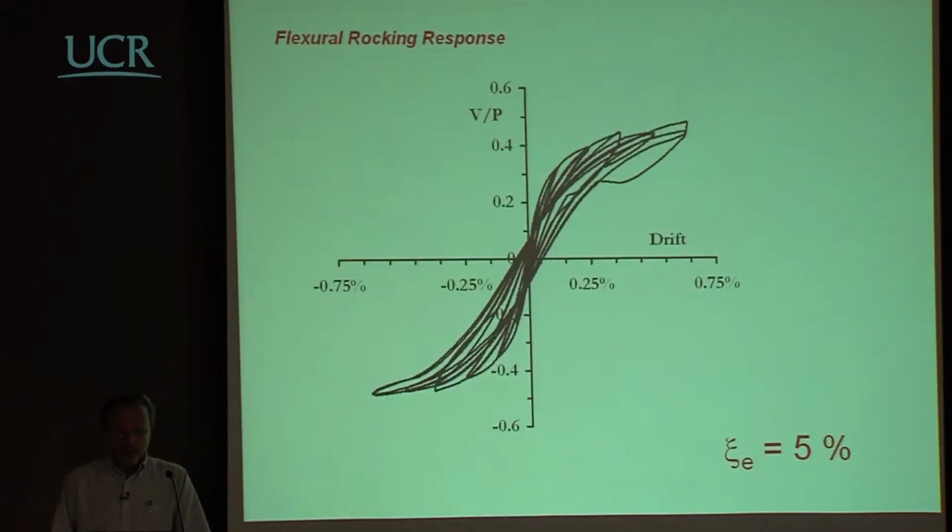Now you go to the laboratory and do some experimental tests, and you see that in this case, this is the kind of cycles that you obtained. That's the reason why you needed to do some numerical evaluation, because you are not sure at what point this will go before starting to crush. And you see that there is quite little damping. This area is small. If you think in terms of equivalent damping, I'll show you in a minute that you will get something in the range of 5% additional damping, not more than that.